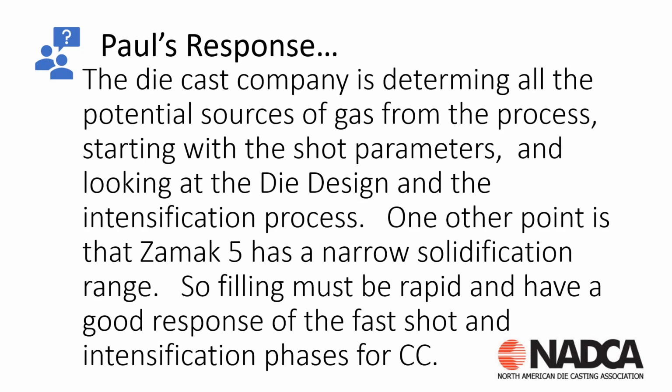One other point I want to make is that they are casting this cold chamber zinc, and Zamac 5 has a very narrow solidification range. So it's similar to casting magnesium. You've got to have rapid fills, and you've got to have a great response, not only of your fast shot system, but your intensification process, so that you're bringing the intensifier in and you're collapsing the gas or moving the gas out of the casting to the venting area prior to solidification.